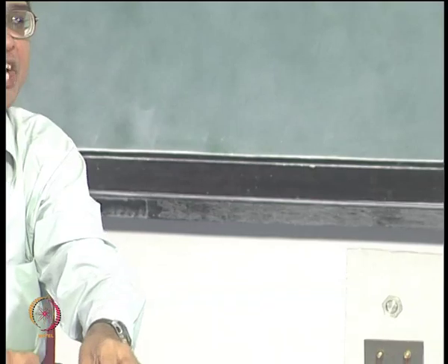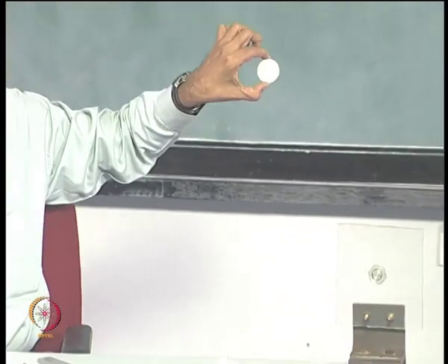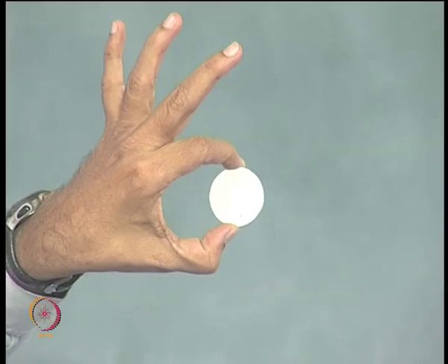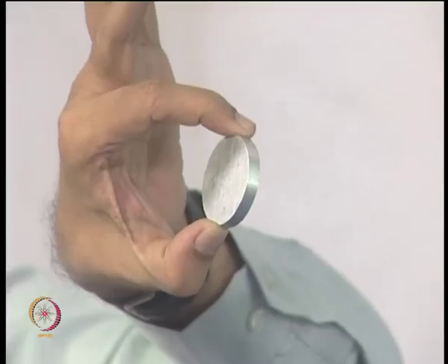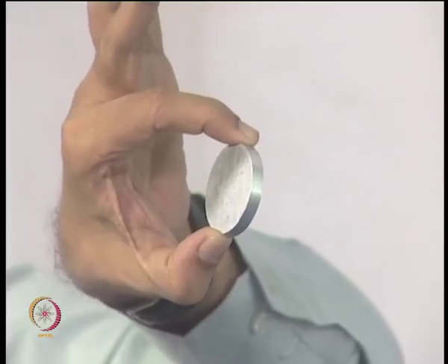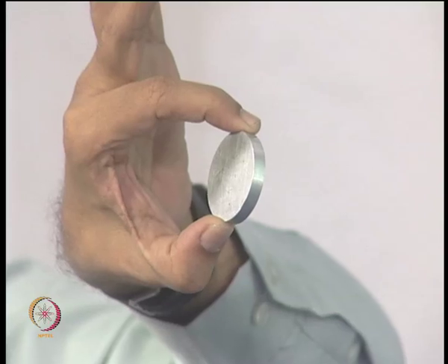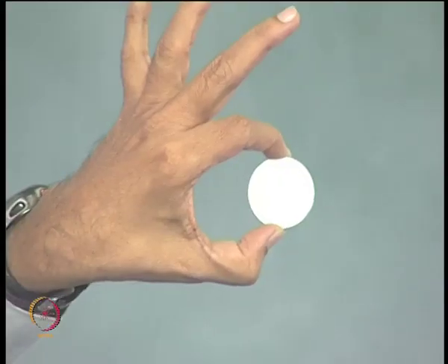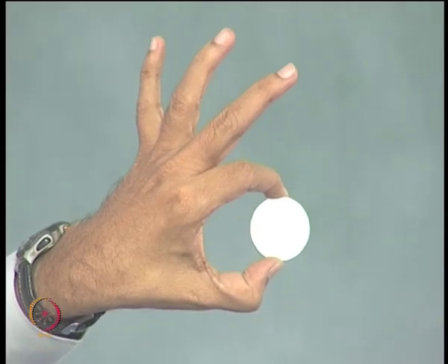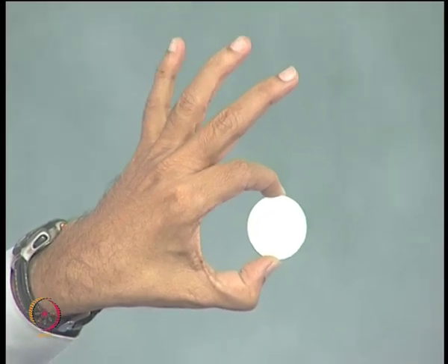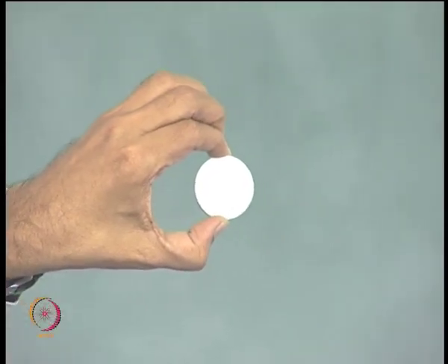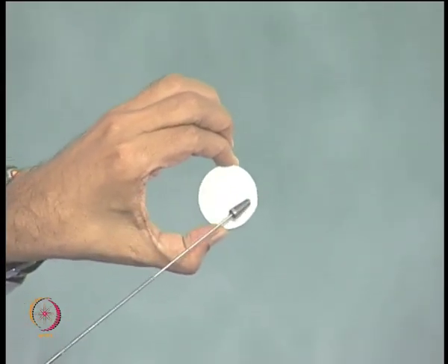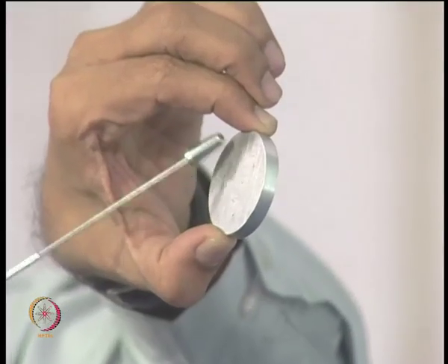Suppose I change the shape to a circle and I put compression. This is the most celebrated model that you use in photoelasticity. You do not have a solution from strength of materials, but you can definitely find a closed form solution from theory of elasticity. I can use the Boussinesq solution and get the stress field at every point in the model.